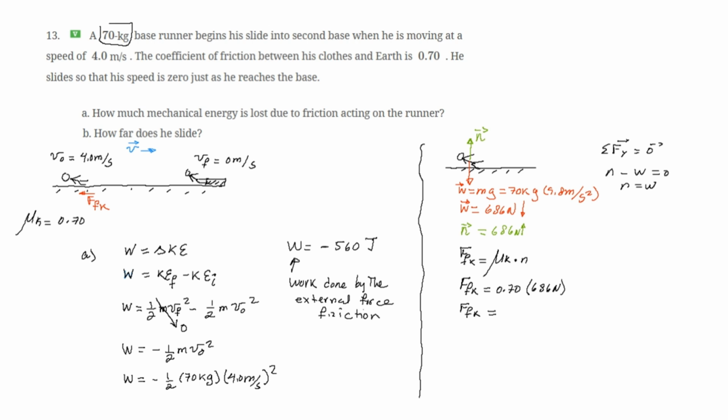We calculated 480.2 newtons, so I would say it is approximately 480 newtons. This is the kinetic friction force.